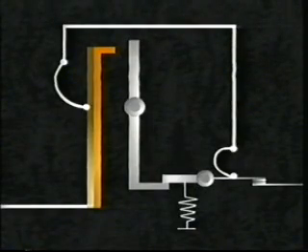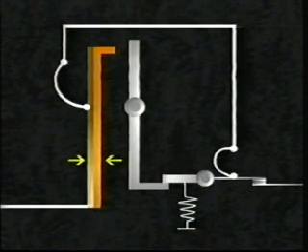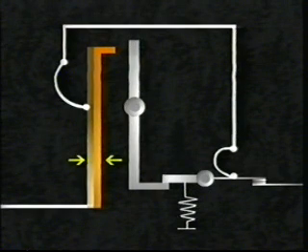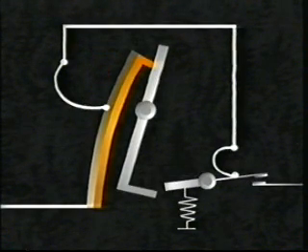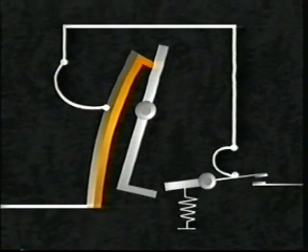Thermal trip action is achieved through the use of bimetal strips heated by the load current. A bimetal strip consists of 2 strips of dissimilar metal bonded together. Each strip has a different thermal rate of heat expansion. Heat, due to excessive current, will cause the bimetal to bend or deflect. The metal having the greatest rate of expansion will be on the outside of the bend curve. To trip the breaker, the bimetal must deflect far enough to physically push the trip bar and unlatch the contacts.